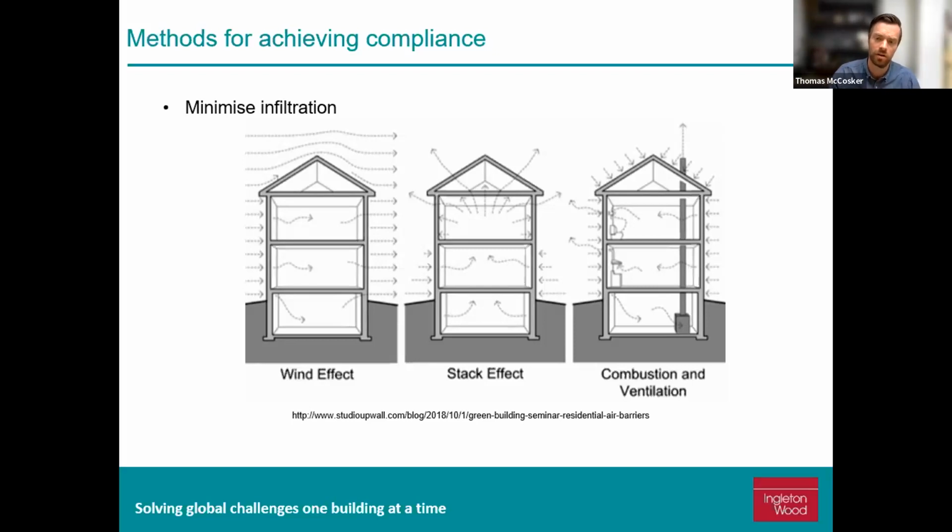Infiltration largely occurs in areas where poor sealing or detailing has taken place. The best way to prevent unwanted infiltration is to target good, and that means low, air pressure test results for your buildings, and ensure the building details are appropriately done so that the builder knows exactly how it's going to be done on this project.